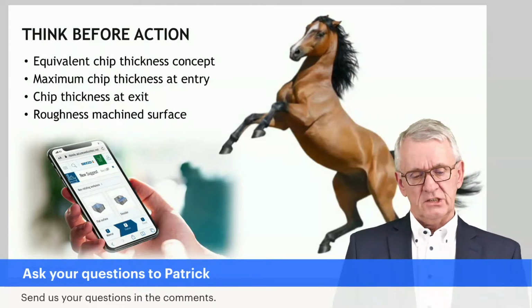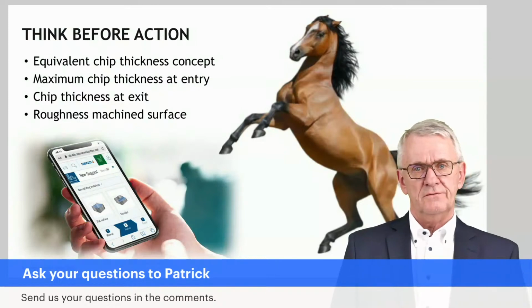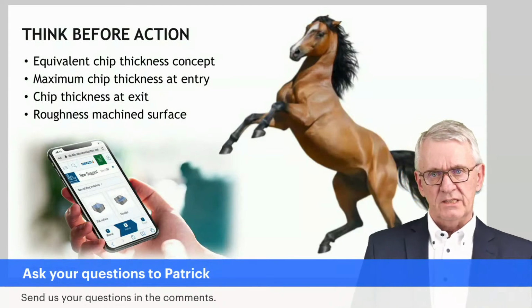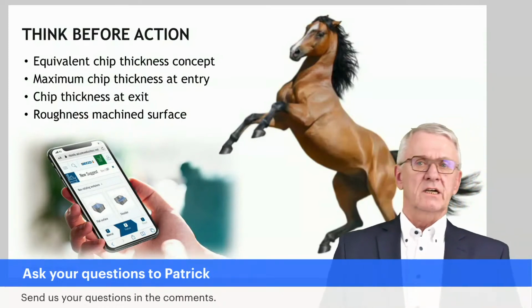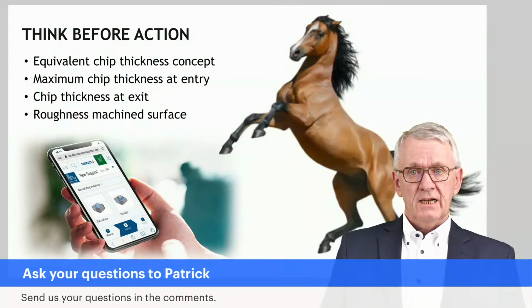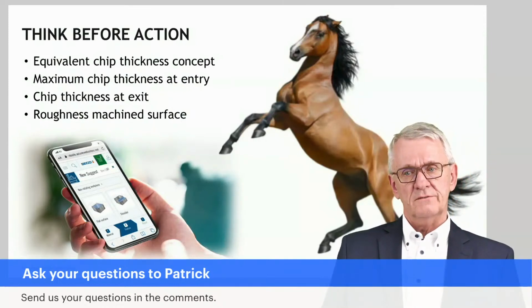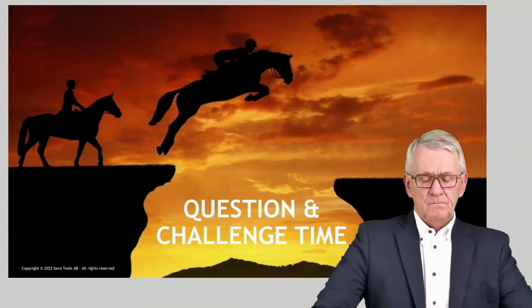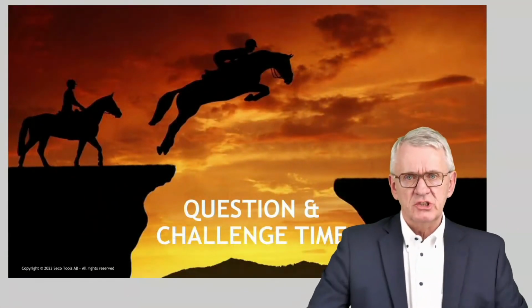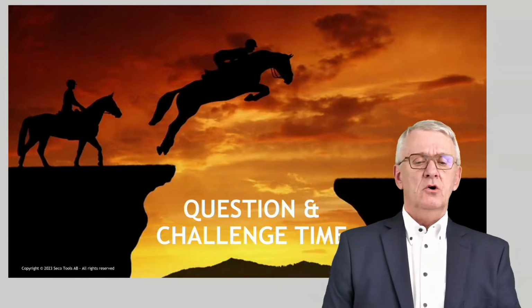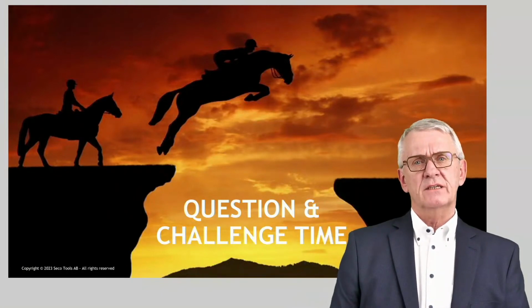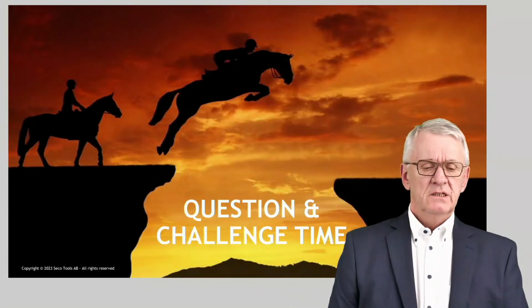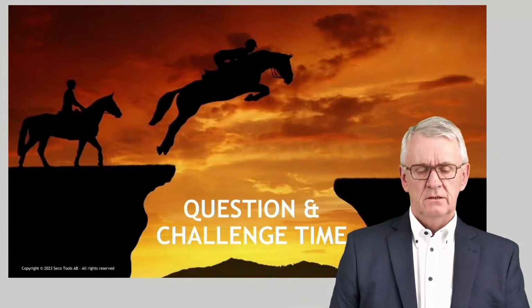And of course, in all these things with increasing the feed and reducing the feed, there is always the surface roughness of the machined surface that plays a role also. It's very nice to say increase the feed, but yeah, there are some constraints to respect when we talk about finishing. Average chip thickness: I hope I made it clear, the concept, why we have it, what we want to do with it.